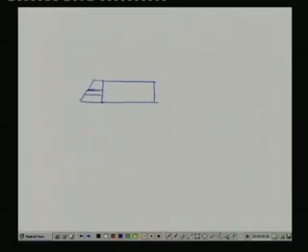This side will be under tension, this side will also be under tension, and if we consider the stress here as sigma, then this side will be sigma plus d sigma. Of course, the neutral axis in the x direction was somewhere here, and this distance we consider as y1. So this becomes the total segment.